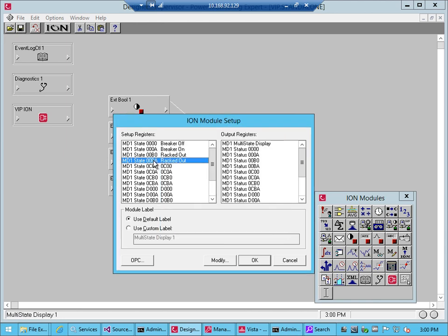So I hope this makes sense. If we see bit 2 asserted, which we'll assume just means the breaker is racked out, anytime that's asserted, independently of whatever the first bit is, the state is racked out.